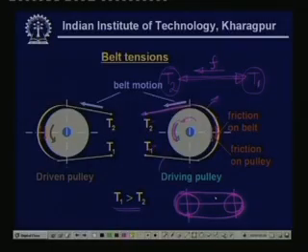But normally, when we consider the flat belt drive, in the majority of cases it will be in a horizontal manner. However, this suggests one important situation: we will always keep the slack side on the top and the tight side on the bottom surface.